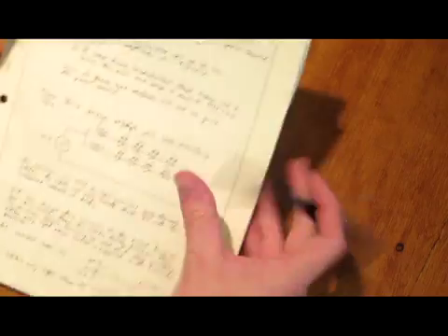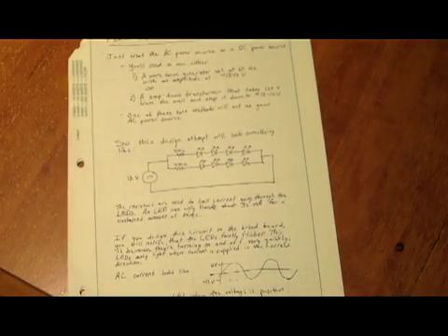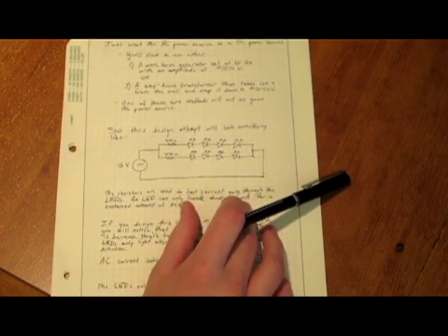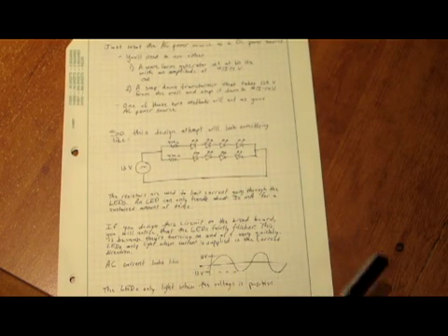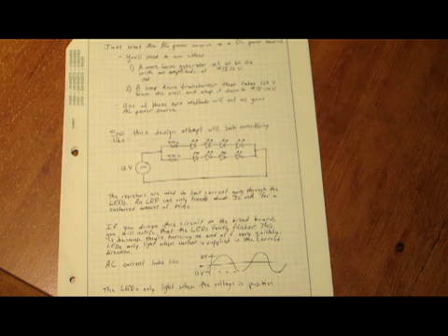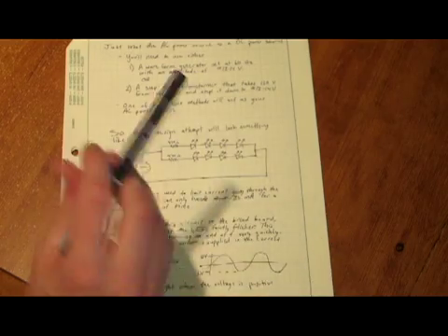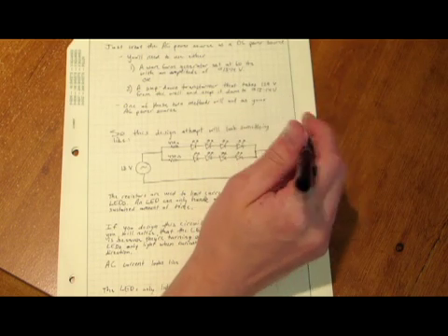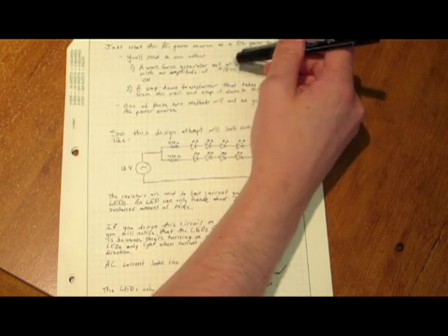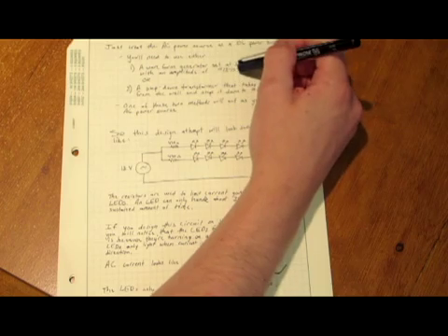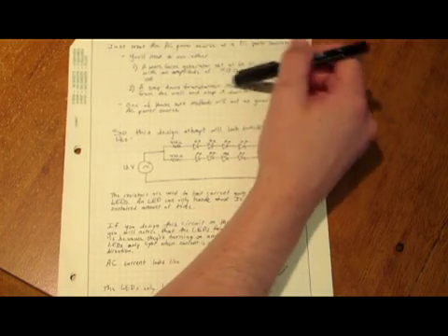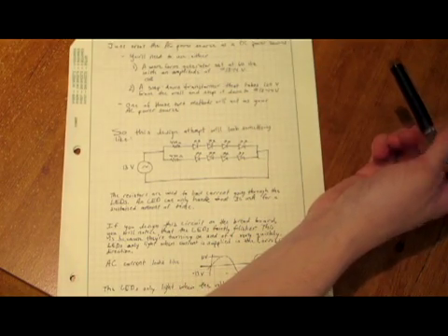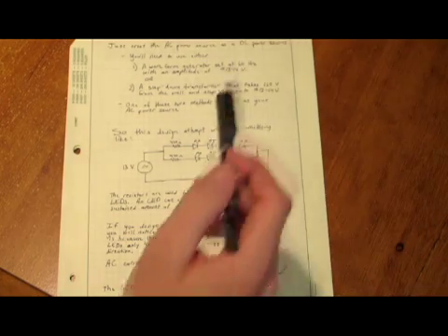Okay, so the point of this project is to power LEDs by converting AC power to DC, but the first couple attempts we're just going to experiment with what happens if you use an AC source in place of the DC source. So you can either use a waveform generator at 60 Hertz and about 13 or 14 volts, or you can use an actual transformer plugged into a wall outlet to get your AC source.